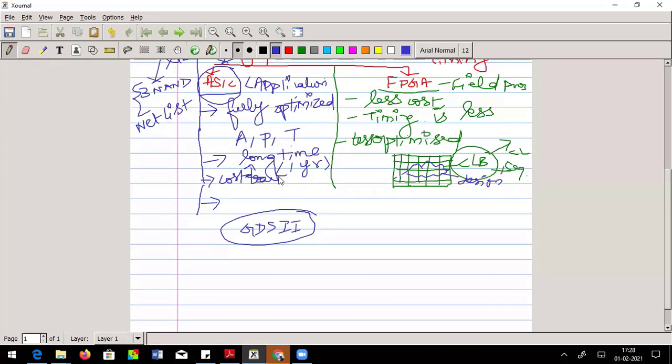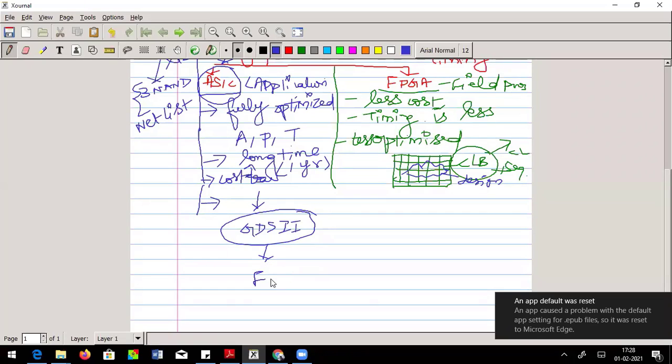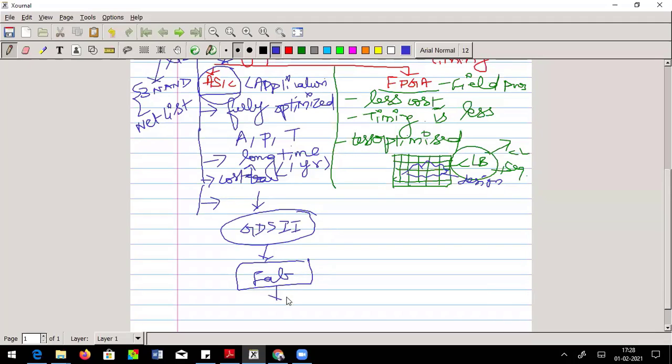In the routing, you have clock, CTS routing, all this. You have, in fact, n number of processes. I'm not getting into that. After completion of all that, the final outcome is the GDS file, which will be given to the fab people, where the fab people manufacture, pack it, and then it will be in the market.